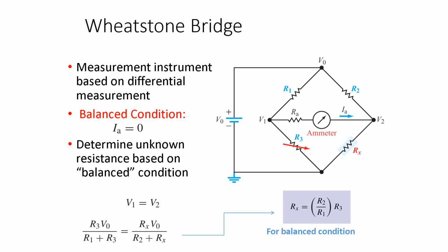Usually the ones that we'll use in class are those where as the temperature increases, the resistance decreases. But we'll look a little bit more at both types. I'm pretty sure I have those already for lab. So with that being said, this equation down below will allow you to determine what that resistance is. And if you know that resistance, there's usually a chart that maps it to temperature. And so that'll give you a very accurate temperature reading.